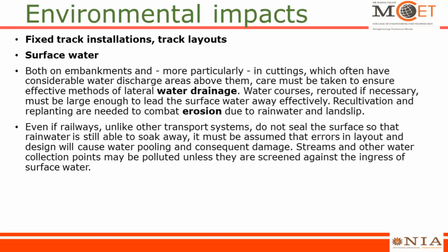So more particularly in cuttings, which often have considerable water discharge areas above them, care must be taken to ensure effective methods of lateral water drainage. Water courses rerouted if necessary must be large enough to lead the surface water away effectively. Recultivation and replanting are needed to combat erosion due to rainwater and landslide.